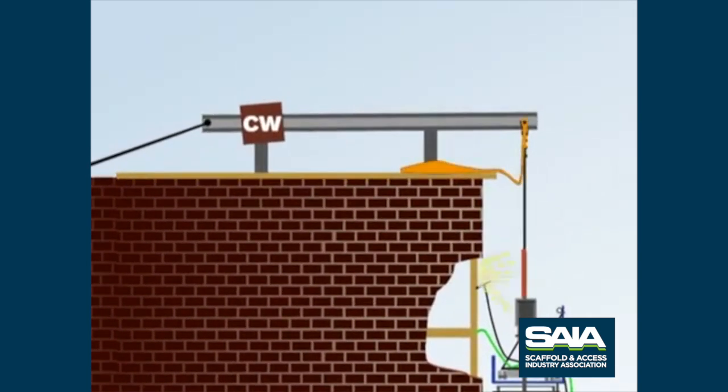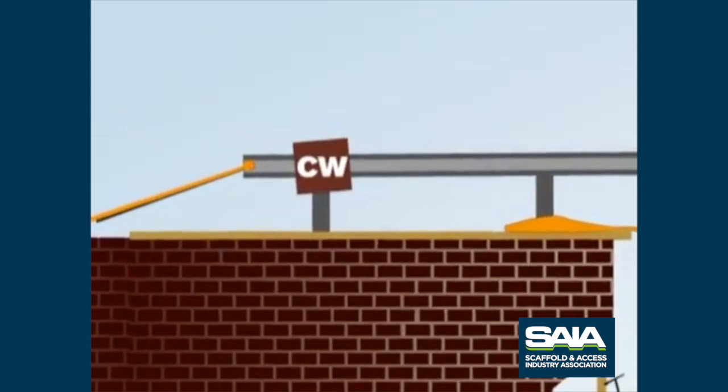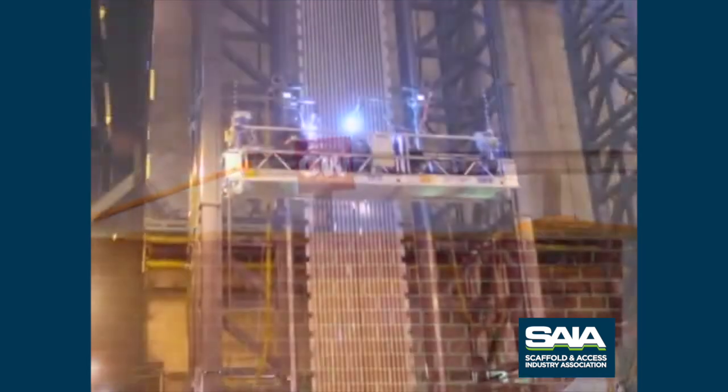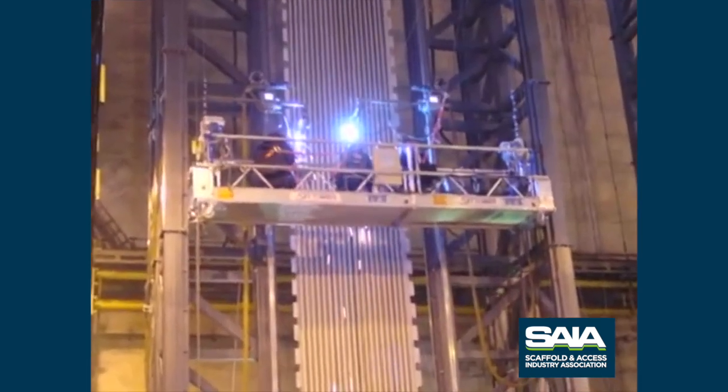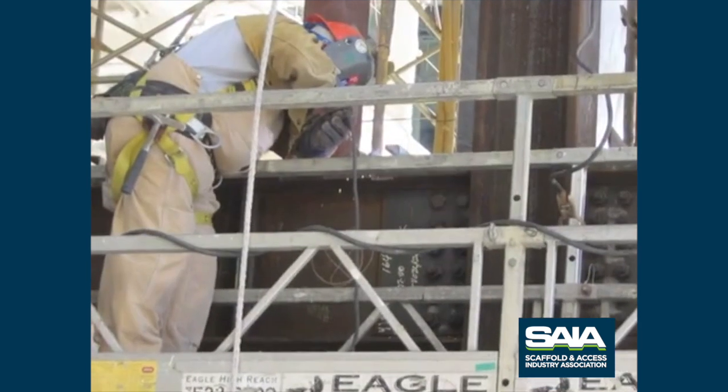Use an insulated thimble on the primary suspension rope and also insulate the tieback rope. Welding near steel wire rope of suspended stages, as in applications such as the one shown here, is extremely dangerous.